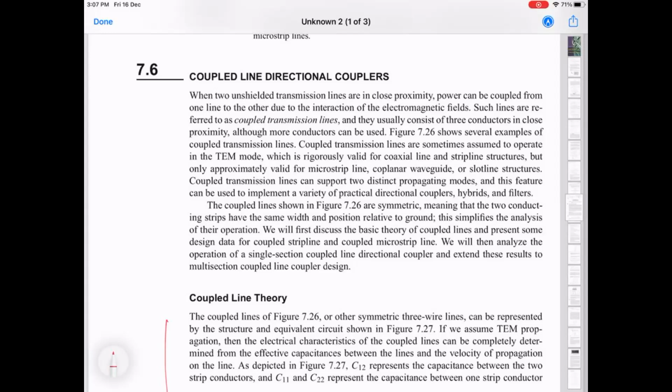So last time, I think we finished with the 180-degree hybrid. We looked at how it can be used to excite differential components. Specifically, we looked at an LC resonator, and we tried to understand the differences between when the LC resonator is directly driven from a port versus using the rat race, which included two main points.